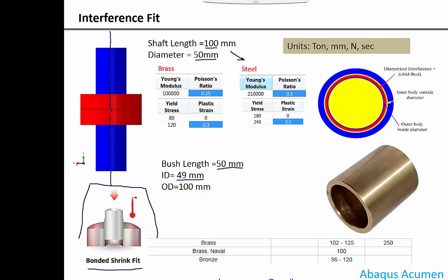Secondly, it is also symmetric about the y-axis, so you can use a symmetry boundary condition here. So we can just take one quarter axisymmetric and directly use that for our modeling. It will be quick and fast, and we are able to generate data with a fine mesh. You can find the stresses generated, contact pressure, so many things you can do.